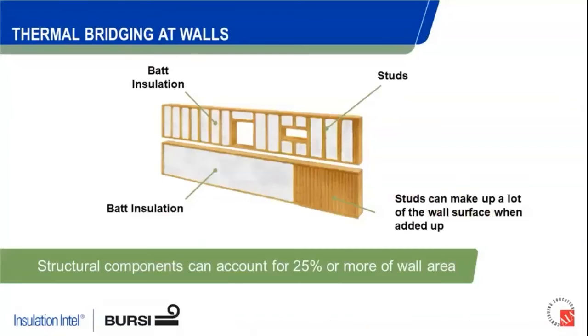a thermal bridging standpoint. And of course, we can't forget about the stud framing in wall systems as well. Whether it be wood studs or steel studs, when we start adding up all those various framing components in that wall system, additional support around windows, doors, penetrations, et cetera, those framing components can easily total up to 25% or even more of the wall area.